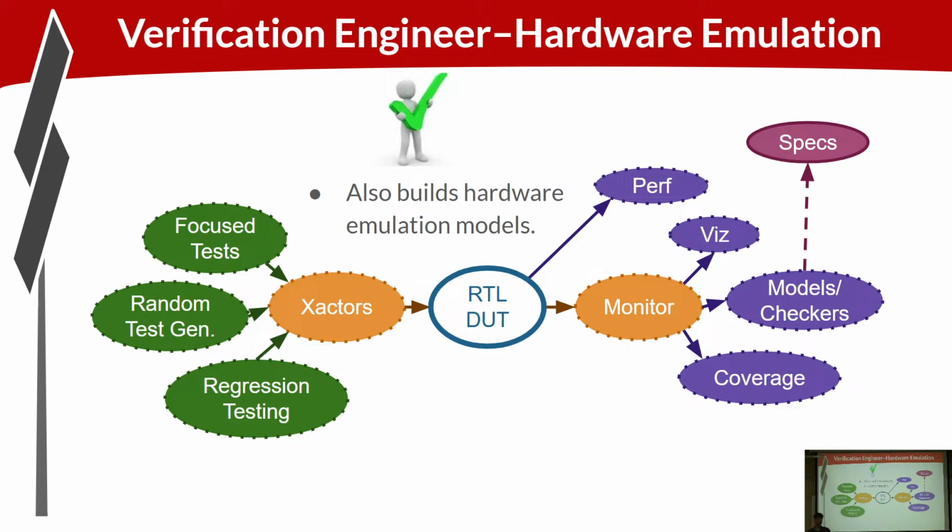So these hardware emulators will have FPGAs for running the design under test. That'll be connected up with a host system that would run the transactors and monitors, etc. Obviously, the FPGA is executing behavior very quickly. Whatever you have running in software is going to run, by comparison, much slower. So the speed of these systems tends to be gated by the software components. So often these components need to be different for the hardware emulation platform than they do for simulation.